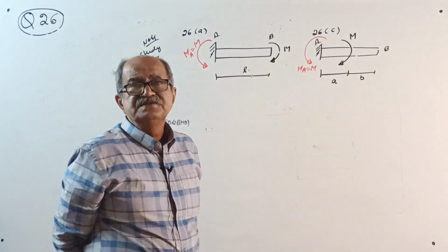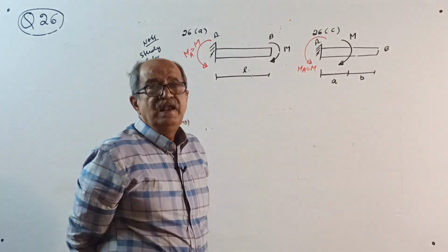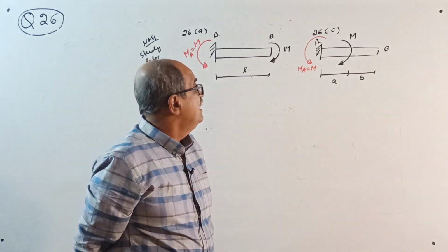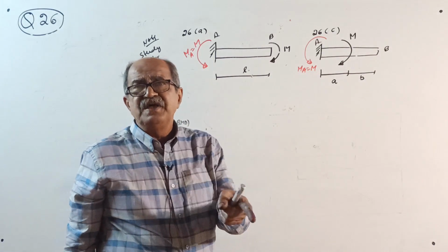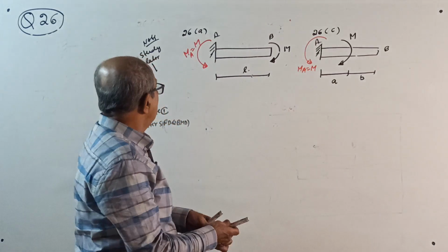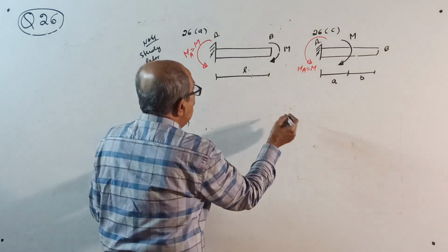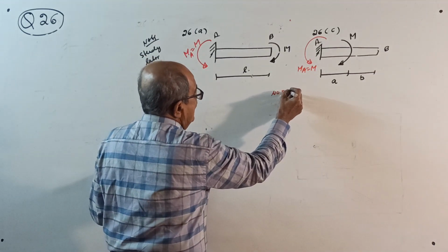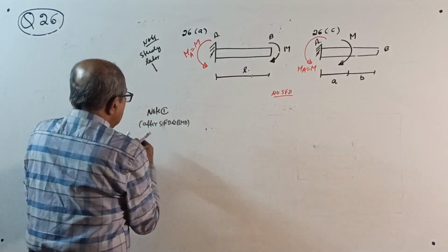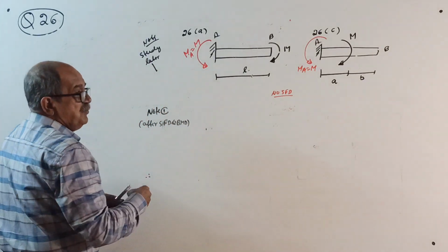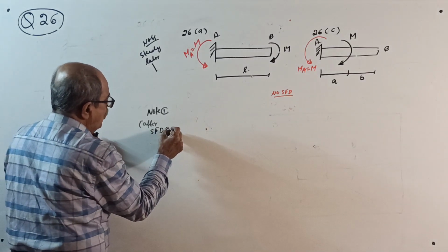But that does not mean that when you go for shearing force and bending moment, and later deflection of beams, you can apply the couple wherever you want. You have to apply the couple exactly where it is given, because for these beams there would then be no SFD. Remember, everywhere shear force would be 0. Study this after your SFD and BMD is over, not now. If you already know it, well and good.